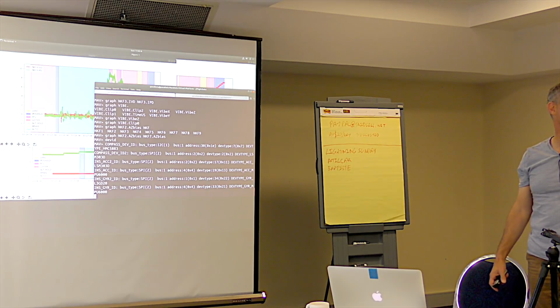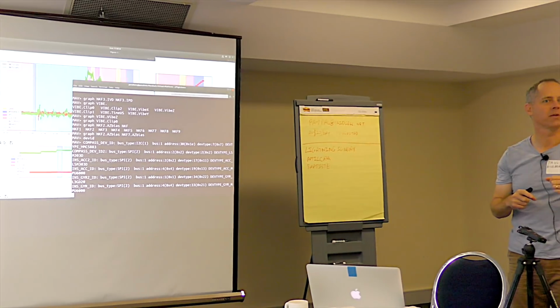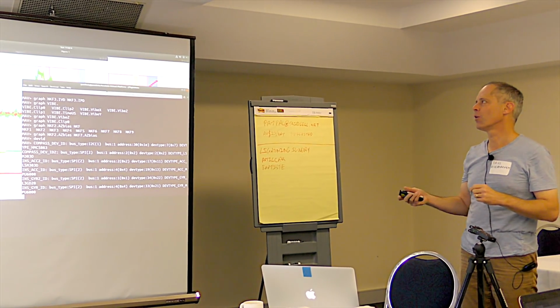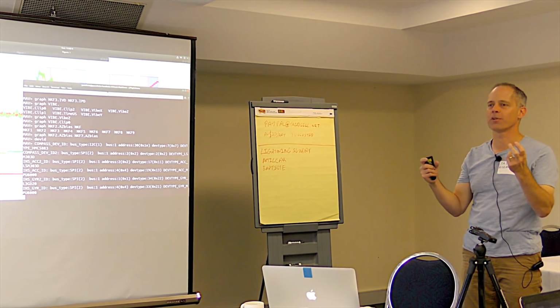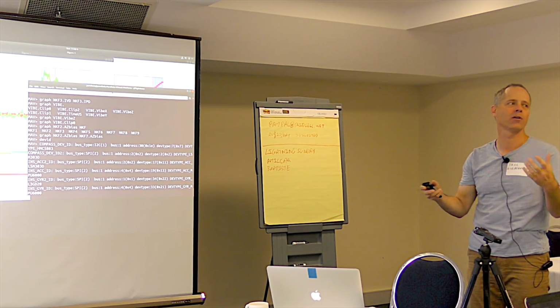Yeah. And this is why we want to move towards one of the things about going to the F7s or H7s with a bit more grunt, or particularly a bit more memory, is that we can basically run EKFs on matrix combinations of sensors and then do a median select on the output from the estimators. So we're no longer relying on, well, I've got two estimators, I'm going to pick them based on this one's going to be primary, and if it goes above this threshold, I'm going to move across.